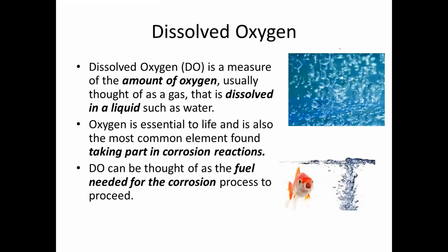The next parameter is dissolved oxygen. So we are somewhat familiar with dissolved oxygen. This is actually the oxygen being trapped in our water. So once this oxygen is trapped in water, it could now cause corrosion. You should remember from our discussion on corrosion that any dissolved gases like oxygen or carbon dioxide could potentially